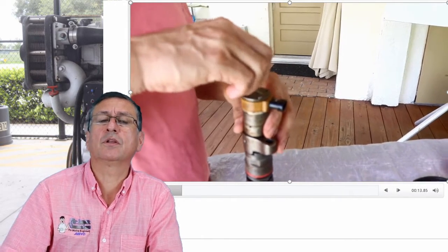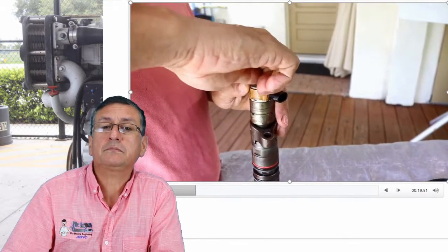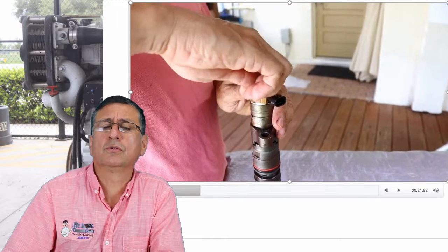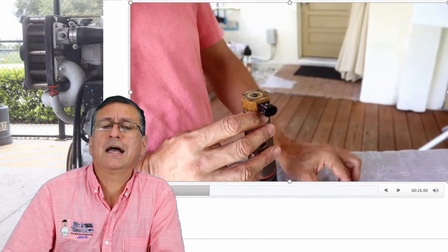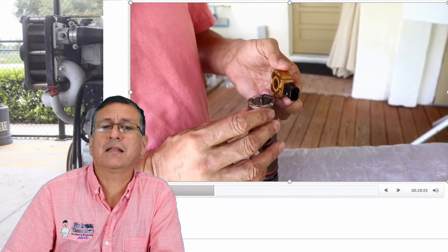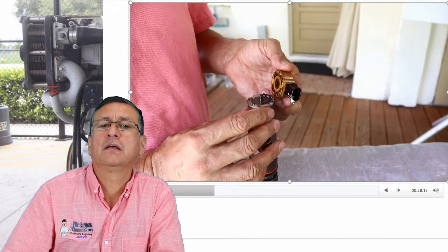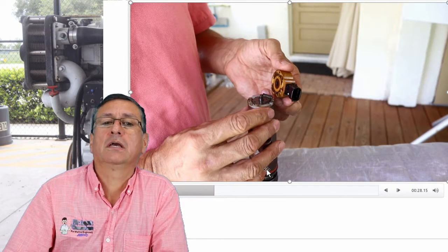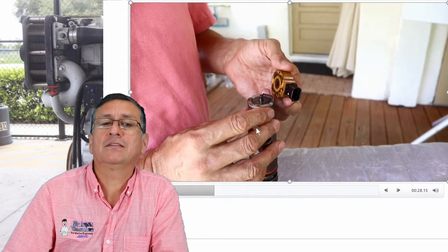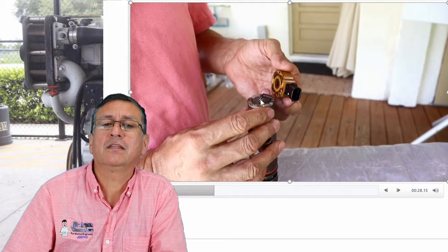We are going to remove the solenoid and we are going to replace the solenoid. Okay, this is the cover. Normally those bolts are longer bolts, special thread. You remove the cover, and this is the solenoid. Exactly, my friend. This is the solenoid that receives the input 4.5 volts, 5 volts, and this is the element, the solenoid. That's the coil of the solenoid. And this is the element that normally is damaged. This one is the spring, and this is the pin.